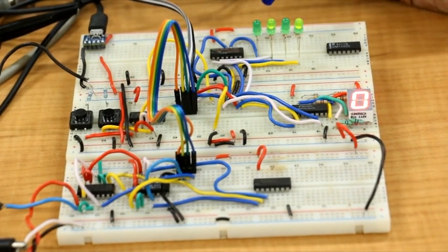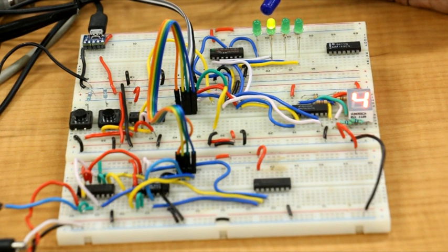Once again, if you look at the logic probes, you can see it's cycling 4, 5, 0, 1, 2, 3, 4, 5, 0. So it keeps on going. Now what I want to show you now, so this is a 1 Hertz clock we have given. So that's why we are able to see it going slowly, and in a very nice way, instead of using a manual clock, we are able to see it cycling through.